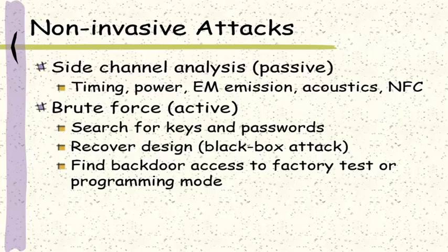By applying high voltage, which normally doesn't have to be very high, just about twice the normal supply voltage, or injecting random signals or commands, attackers may gain access to factory testing or programming mode. These accesses are sometimes known as backdoors.